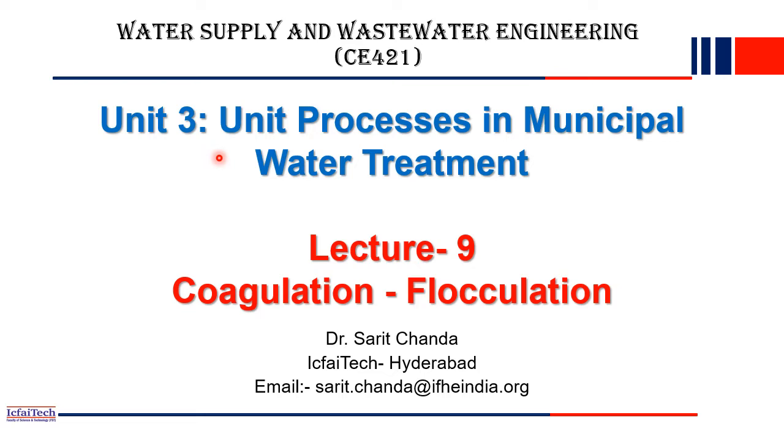Now, after aeration, water goes into the primary sedimentation tank, and here also we have seen the principle of settling, how the solid particles simply settle down to the bottom because of the force of gravity. We have seen the different types of sedimentation tanks, a circular one or a long channel type basin. All these things we have discussed in detail.